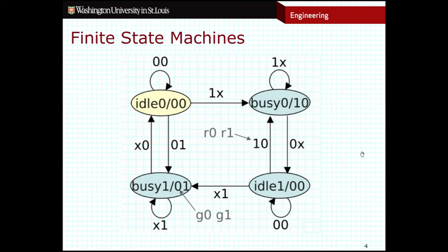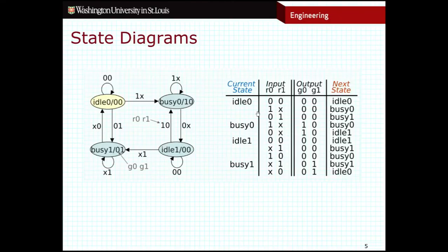So once you are satisfied with the operation of this finite state machine, I'd like to show you a few other things that you can do with finite state machines. The next thing to take a look at is a transition diagram. On the left side here, you see we have our fair arbiter finite state machine. On the right, we see a transition diagram for this machine.